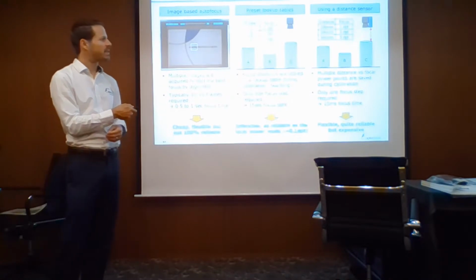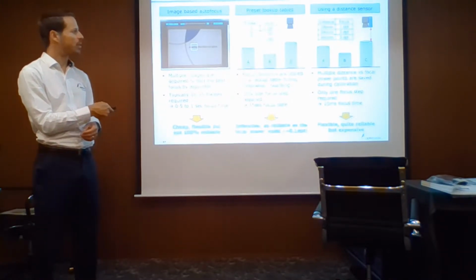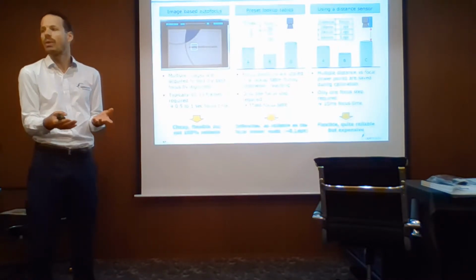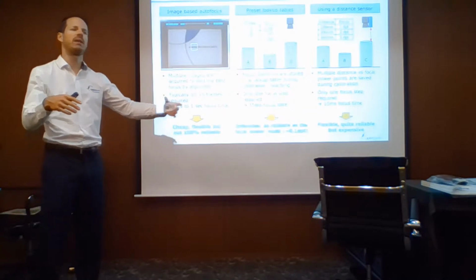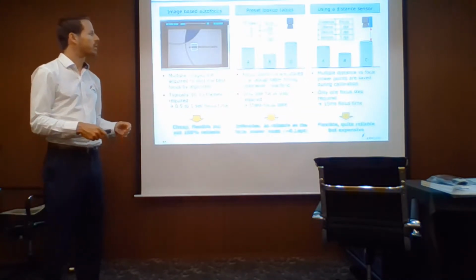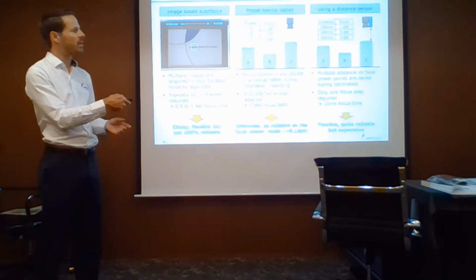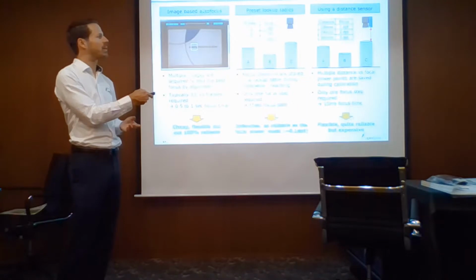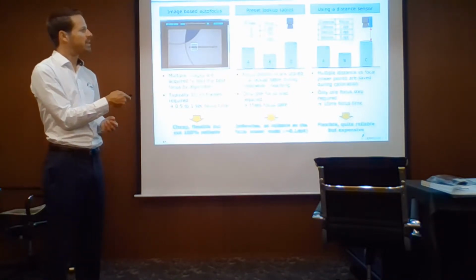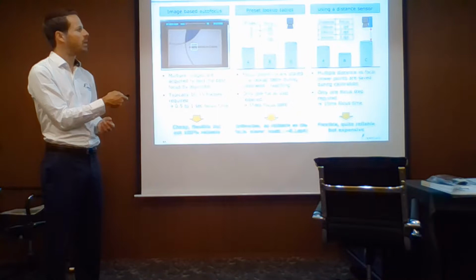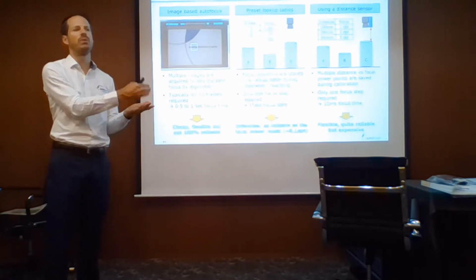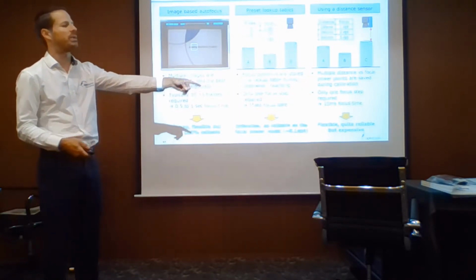And then with the distance sensor, it's kind of the same thing, except the PC or the system does not know what's coming, like maybe in package sorting in logistics, where you have different boxes. The computer does not know what's coming, but the sensor is going to give a signal that can be related to the optical power. So here the lookup table is basically different distances having different diopter values, but actually if you use the analog in, instead of distance, you have a voltage. And you do a lookup table from a voltage to the optical power. And that's exactly what the demo does over here.